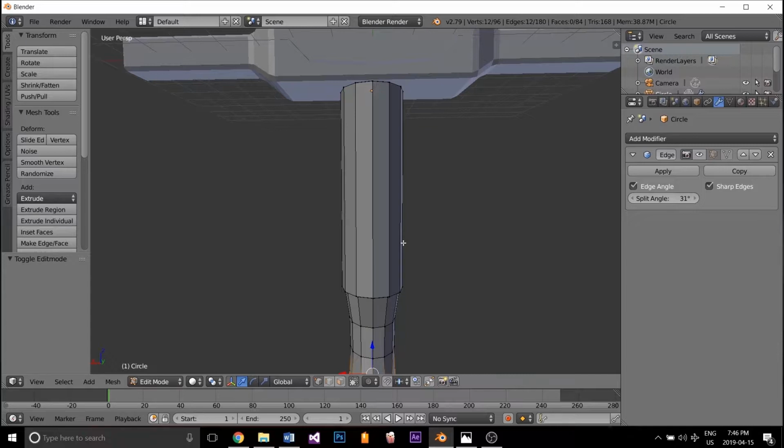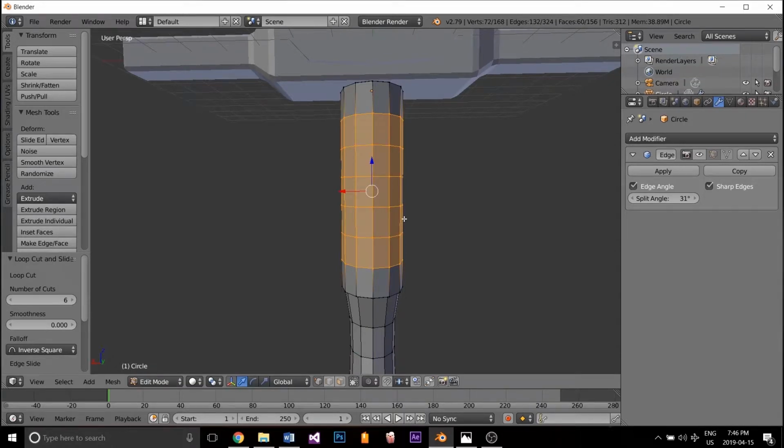To do this, I'm going to continue in with adding loop cuts. So if I click Control R, I can actually now put in my specified segments too. So the segments that I think that I'm going to need, I'm going to use 6, maybe it looks like. Yeah, that'll do. 6. I'm going to left click twice to finish my selection.